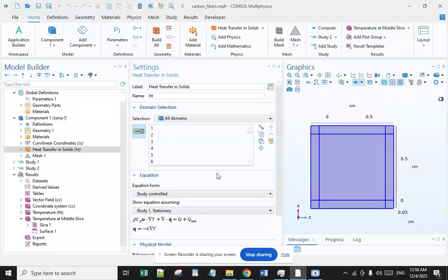The next step is the determination of the transverse conductivity for all fabrics, the analysis of which is presented here, and the results are presented in this numerical result, starting with NCF 300 biaxial, a transverse thermal diffusivity of 0.15 multiplied by 10 to the power of minus 6, determined from the gradient of the linear data fit, yielding a thermal conductivity.